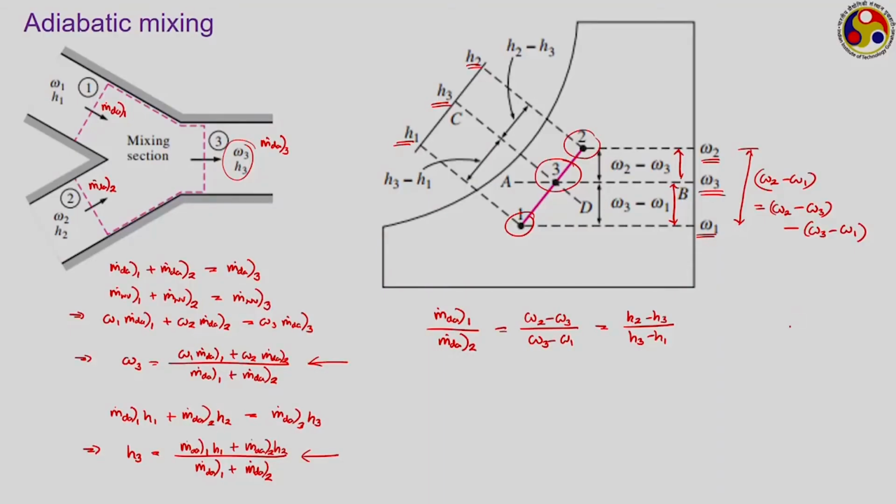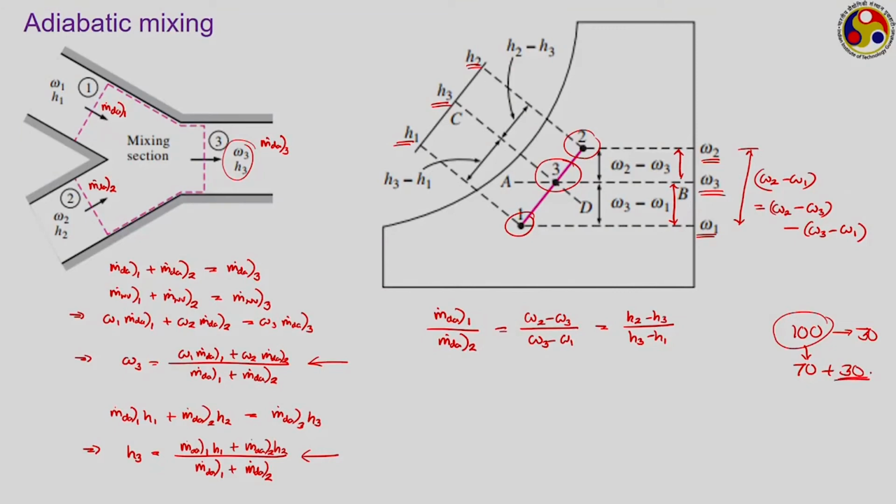And it is very much possible, like suppose we are taking say 100 units of air back from the room via the exhaust, maybe only 30 units of that goes to the surrounding, the remaining 70 units comes in and gets mixed with 30 units of fresh conditioned air, and subsequently the entire 100 units of this mixture comes back to the room. So, if we are rejecting or exhausting this entire 100 units of air, then your air conditioner has to condition 100 units of air again. But in this situation, because of the mixing, we just have to condition only 30 units of this.